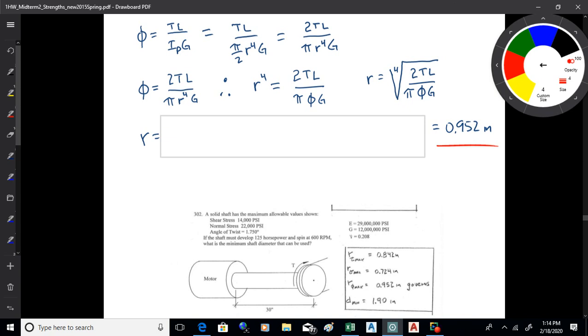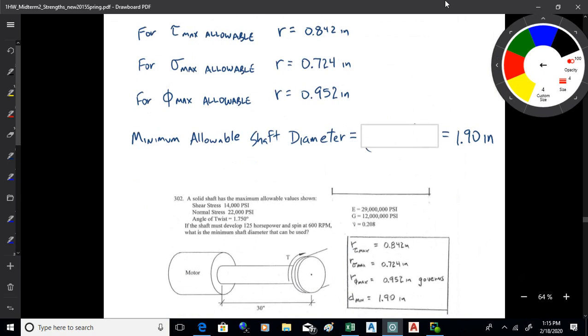And then you've got 3 different shaft sizes now that are required. Each one is the minimum or absolute required shaft size for the different thing you're analyzing. So what that means is you pick the biggest, right? Because when you do design, you pick the lowest load, because that's the safest load. You pick the biggest size, because that's the safest size. So you pick the biggest one, double it, because you solve for radius, but you spec shafts and other round things, you spec them on diameter.